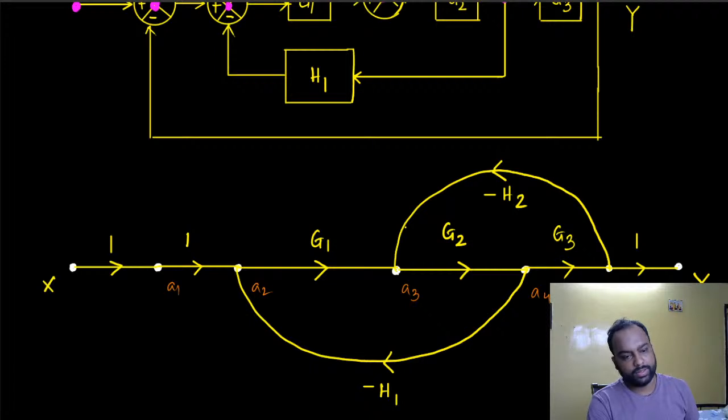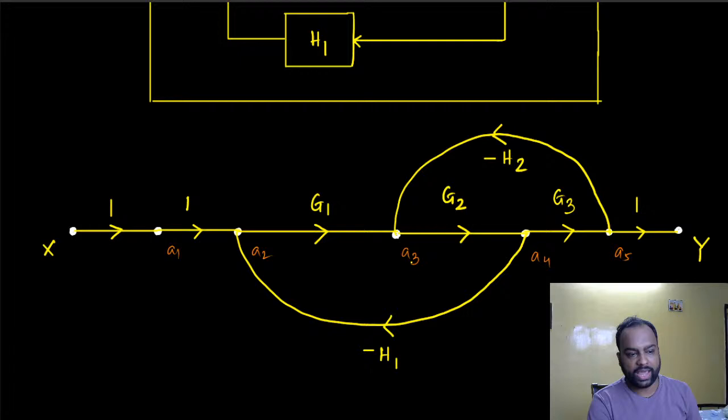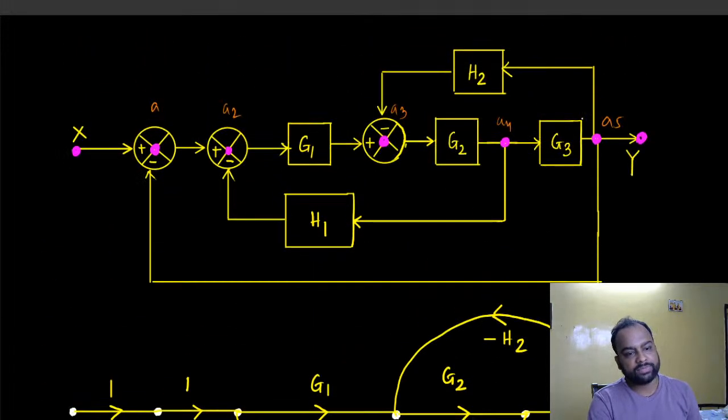All right, so that's understood, I think. So from A5 into A3 through a transfer function of minus H2. Whatever signal comes out of this point goes through this transfer function, which is minus H2, and gets summed up at A3. Essentially we haven't modified the behavior. All right.